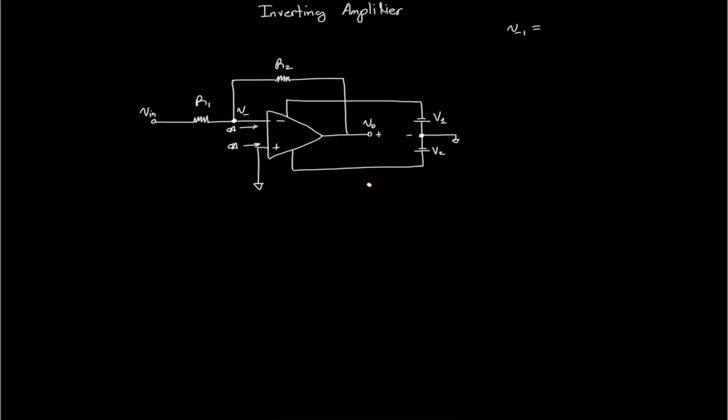If I set V out equal to 0, I would then get the voltage across R2 with reference to V in, by voltage division. Then for V minus 2, set V in to 0, take the voltage across R1 with reference to V out, and that will be V out R1 over R1 plus R2. Then by superposition, we can add both of those together.